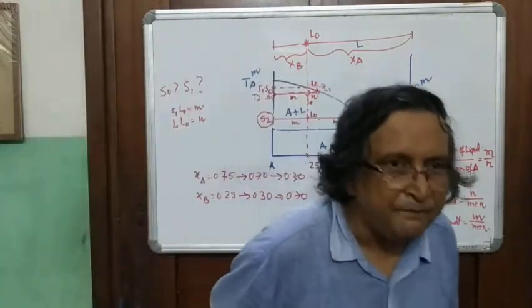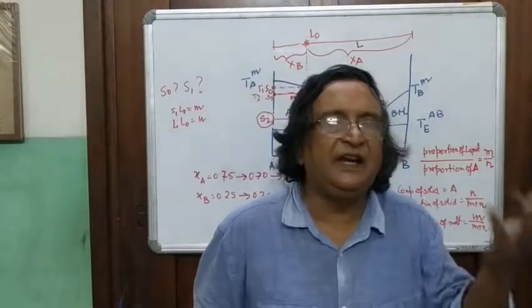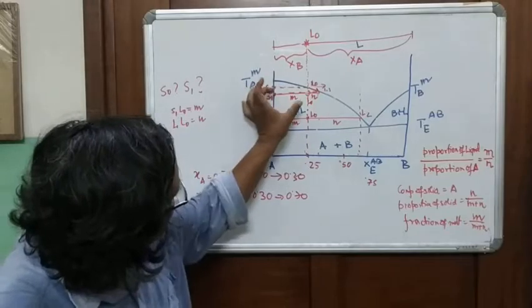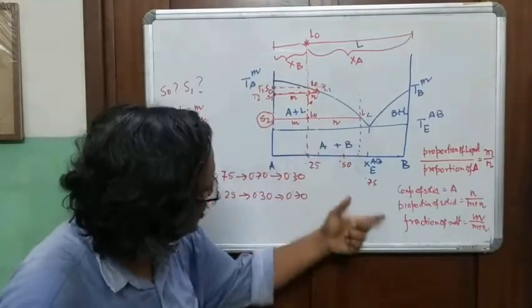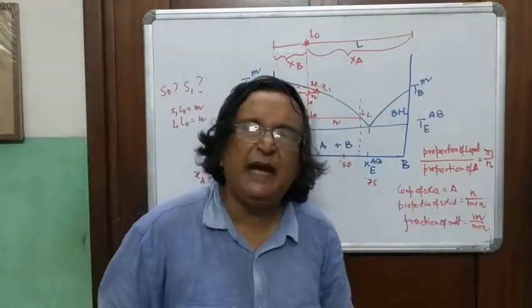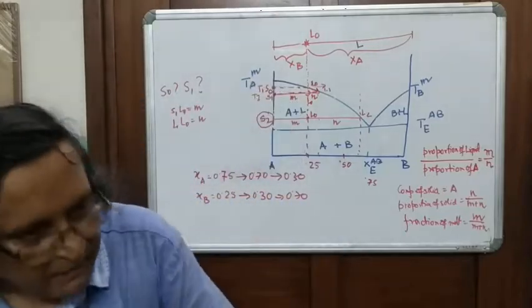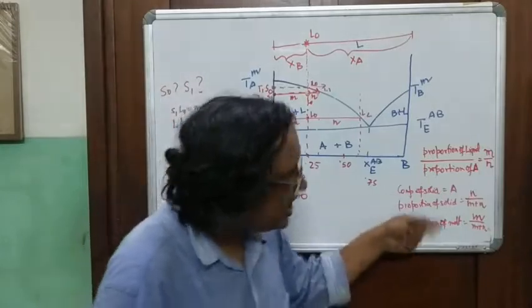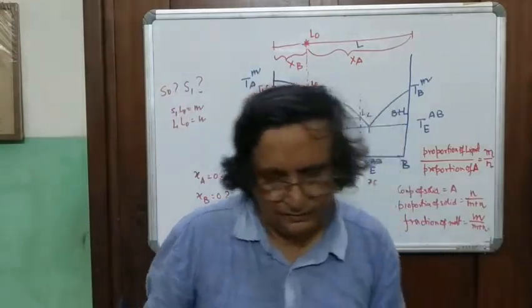At the same time, the fraction of liquid, M divided by M plus N, you see this is small but this is becoming larger, so the fraction of melt is decreasing because more and more solid is increasing, or the fraction of solid is increasing.